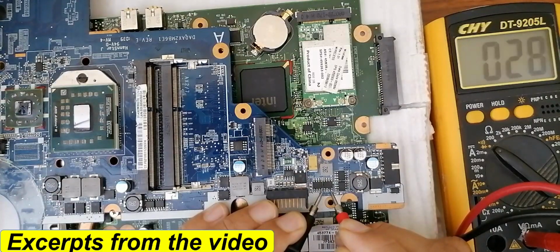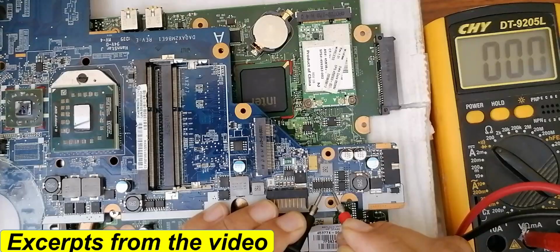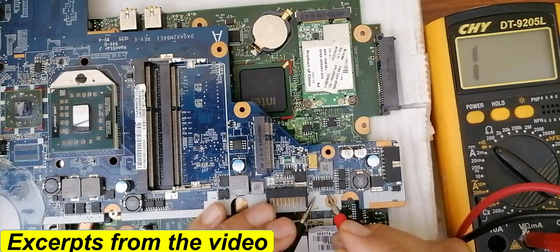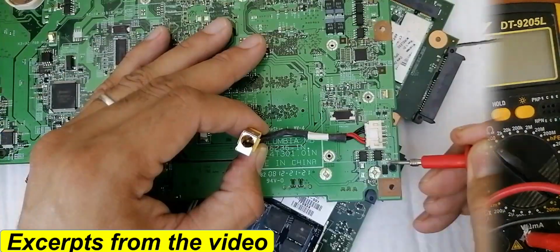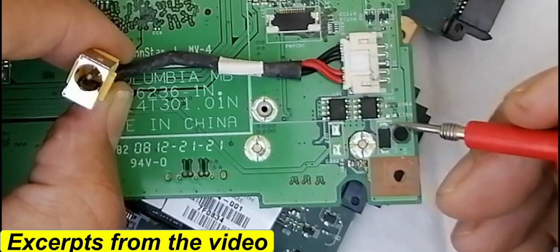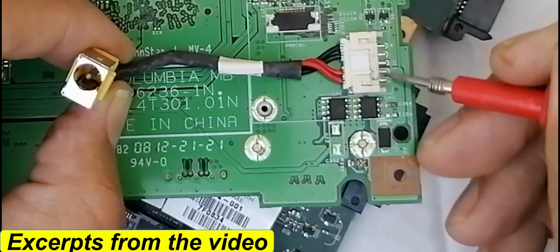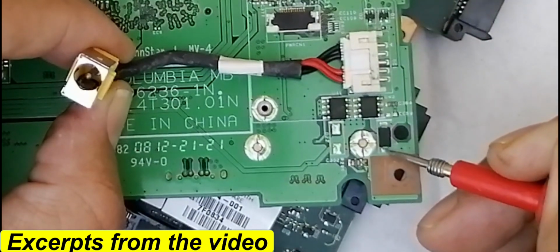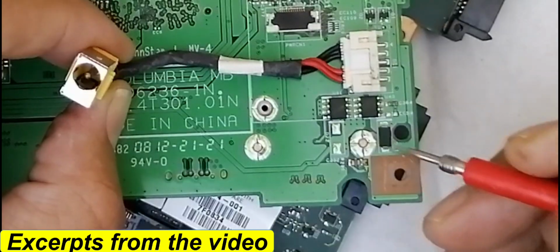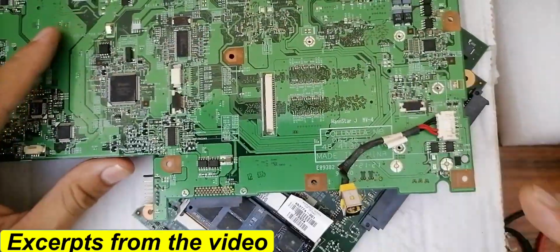So the 3rd pin also has continuity, a beep. The 4th pin, as you can see. So 4 pins are connected together. This is the cathode. As you can see, we have this white mark here, which means this is the cathode. This part should be connected to these terminals here, and this part should be connected to the ground because this is a protection diode. So let's use the multimeter and check this diode.